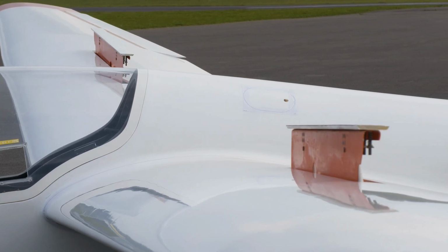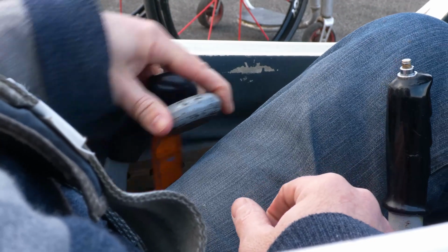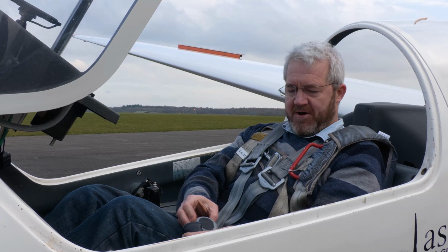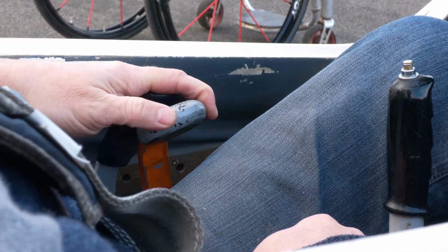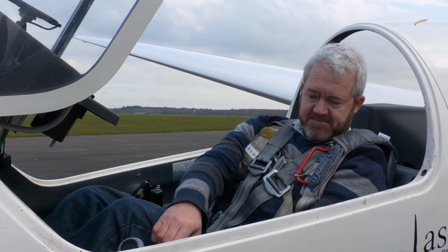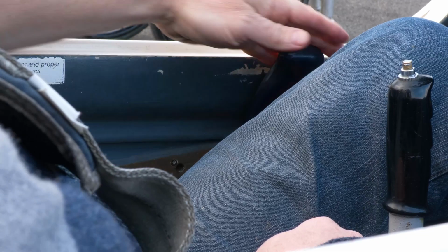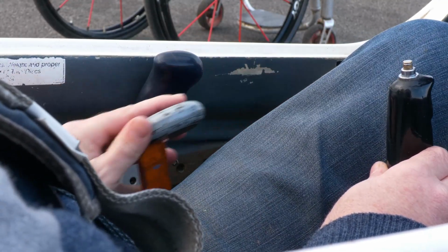Now this itself presents further problems, because during the landing approach, another control that needs to be used is the air brake. Now, the air brake is controlled also by the left hand, and this presents a problem because the glider pilot needs to use the air brake and the hand rudder at the same time. So to overcome this problem, there are notches built into the side of the glider and a stud on the air brake, and this can be notched in position, and then the glider pilot is free to use the rudder to control the aircraft.